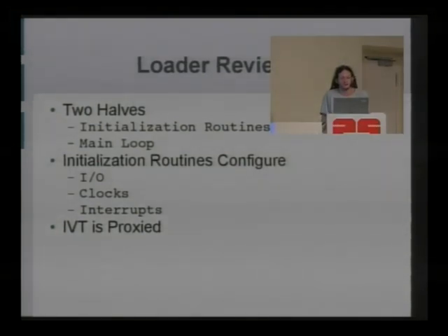And if you don't configure the I2C bus properly, then you break it for everybody, and then the USB to serial chip can't function. So if you were to just write a simple blink the LED firmware image and place it within this chip, the board would cease to function on the USB port.